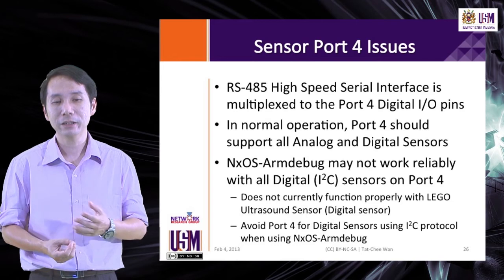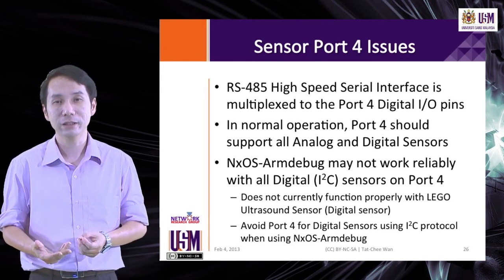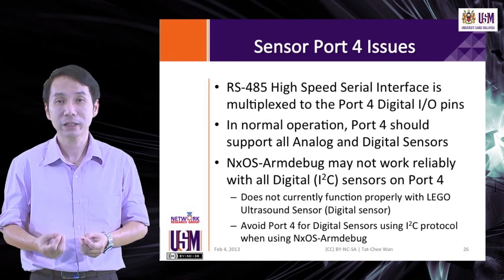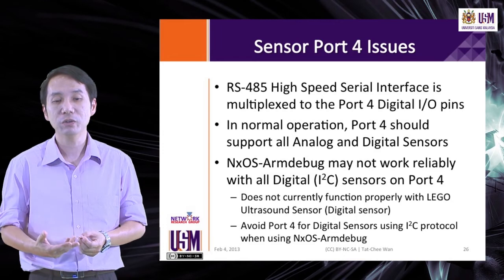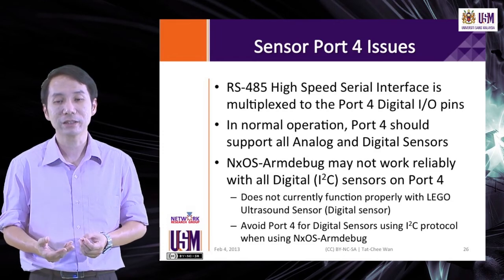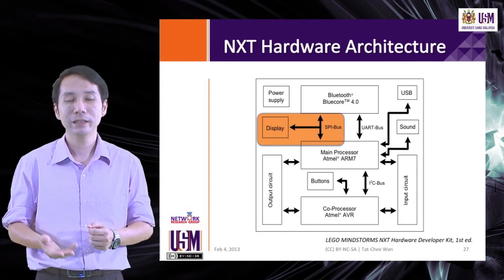So in our case, we found that it does not currently function properly with the LEGO ultrasound sensor, but it may function with other third-party sensors. So for safety, it is best to avoid using port 4 for digital sensors using the I2C protocol when using NXOS ARM debug. Next, we look at the display interface.